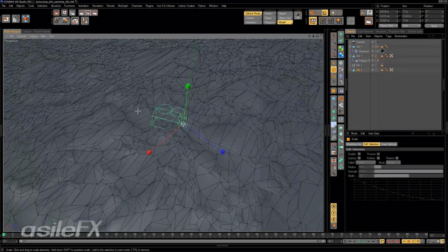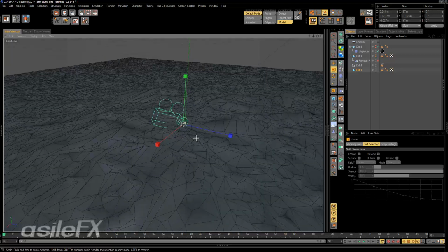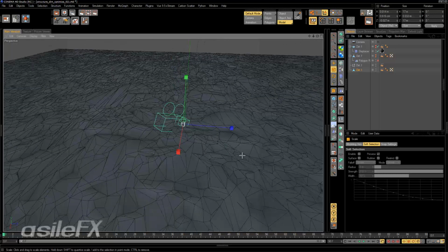And then you can further reduce the polygon count if needed. I had a reduction of about 95%. You can bring it down further than that. It really just depends on the object you're populating on. In this case, it's a little easier because it's more like a terrain. So we've got a lot more flexibility for the reduction, and it really won't take much.